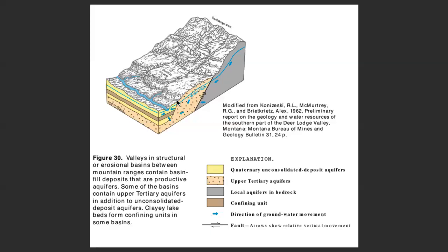All right, then we move out into the quaternary deposits. And these are where our big aquifers are. So the Missoula aquifer is in the quaternary, unconsolidated alluvium. And they're directly tied to the river system. So these are shallow. They're usually less than 100 feet, maximum up to 300 feet. And they're in direct communication to the local river system. So the Missoula Aquifer, maximum depth is 100 feet.